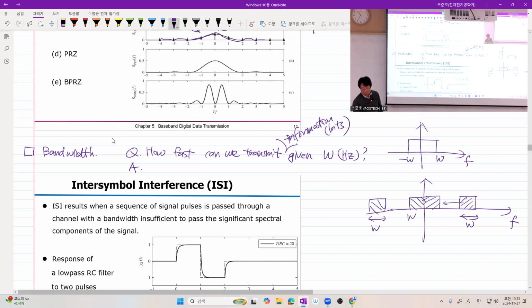Then what's the difference between this and that one? Mathematically speaking, having a communication channel with bandwidth W in real baseband is, if its response is flat, the same channel as this real passband channel with bandwidth W.